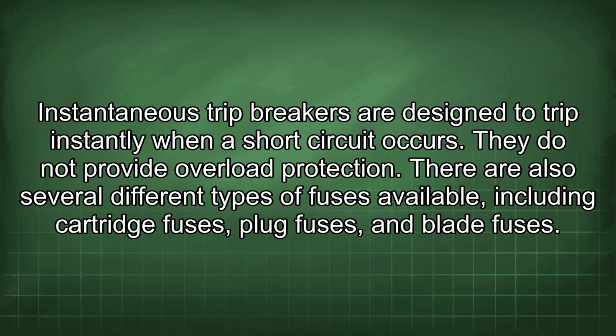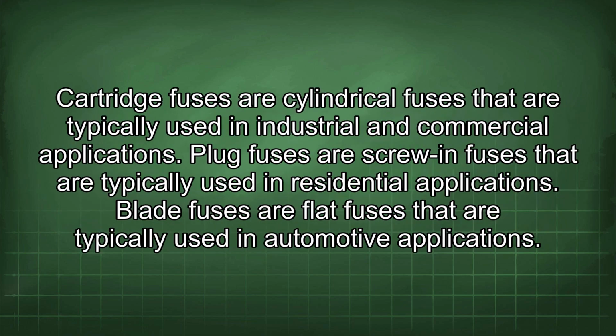There are also several different types of fuses available, including cartridge fuses, plug fuses, and blade fuses. Cartridge fuses are cylindrical fuses that are typically used in industrial and commercial applications. Plug fuses are screw-in fuses that are typically used in residential applications. Blade fuses are flat fuses that are typically used in automotive applications.